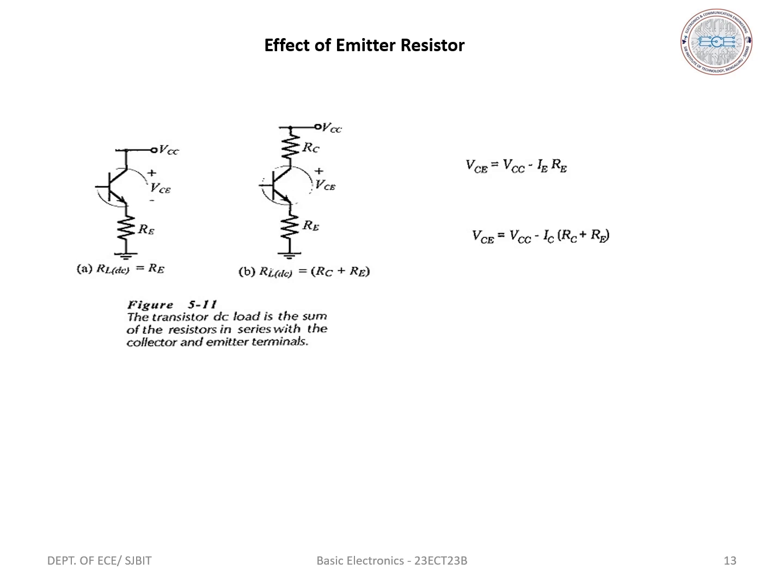Simplifying that, we get IC equals minus 1 by RE into VCE plus VCC by RE. If we put IC equals 0, then VCE equals VCC, and if we put VCE equals 0, then IC equals VCC by RE. Those two are the DC load line points.